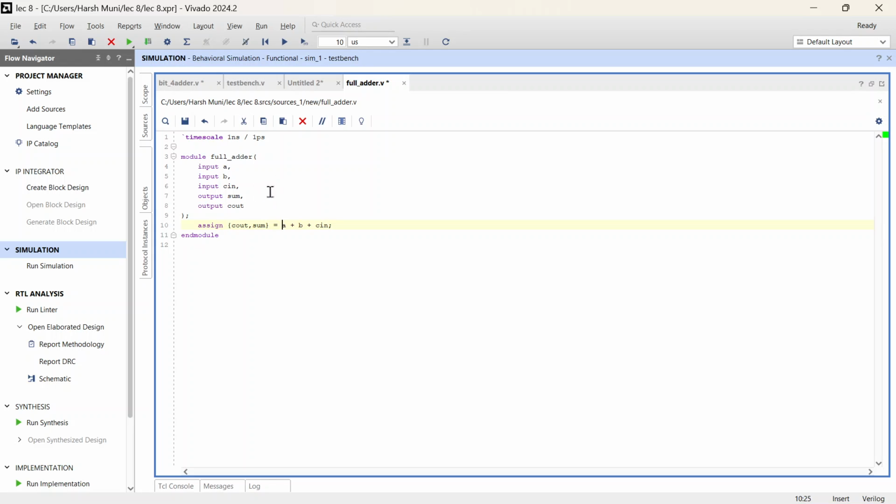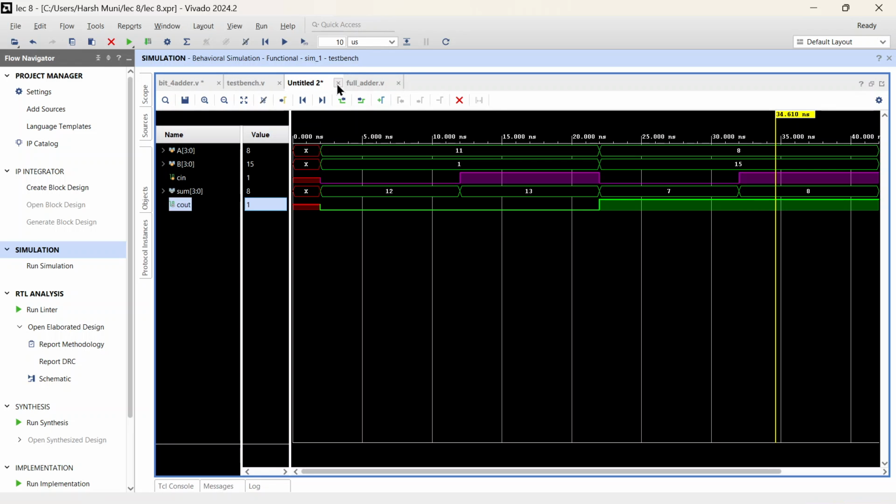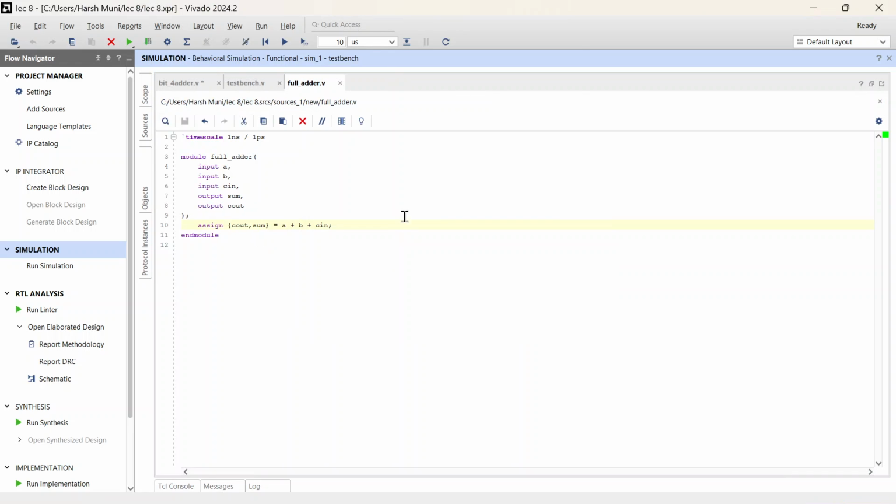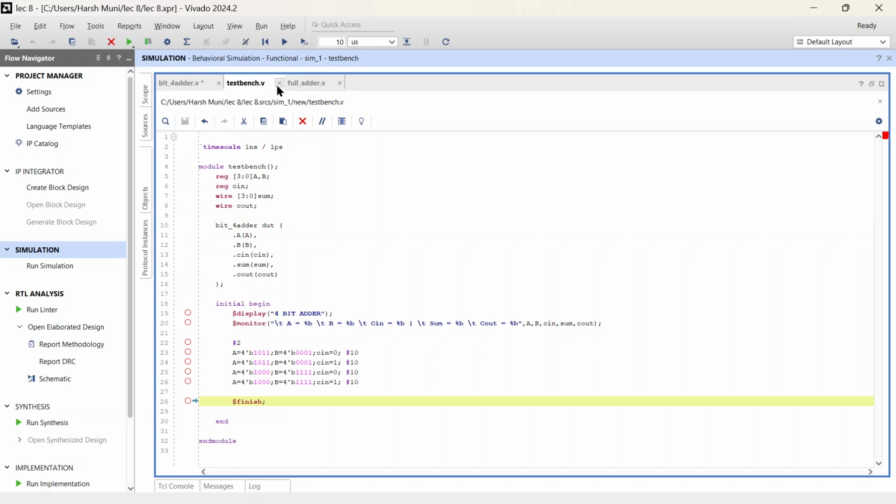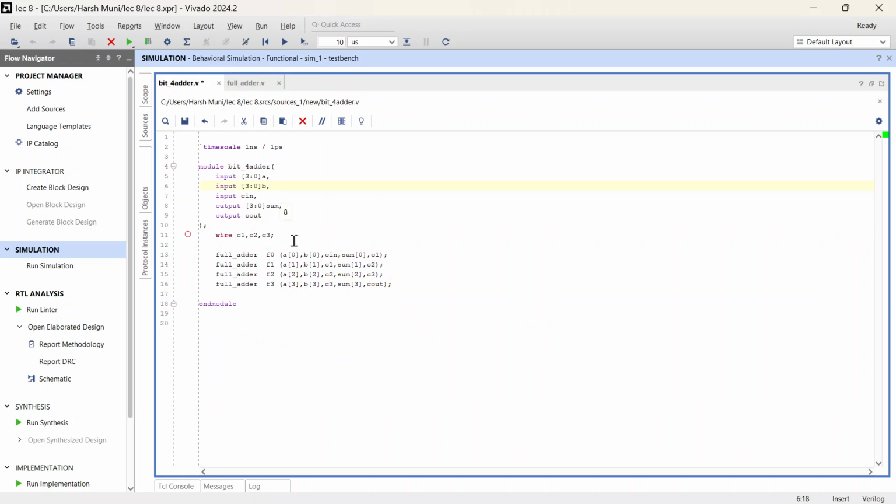So we did it, just need to save it here. We named it full adder. Let us remove this schematic discard here. Now we created a full adder. Now let us remove the test image now. It will give the same output that we see. So we created a 4-bit adder, full adder x1, x0. So we assign the ports corresponding to the input values.